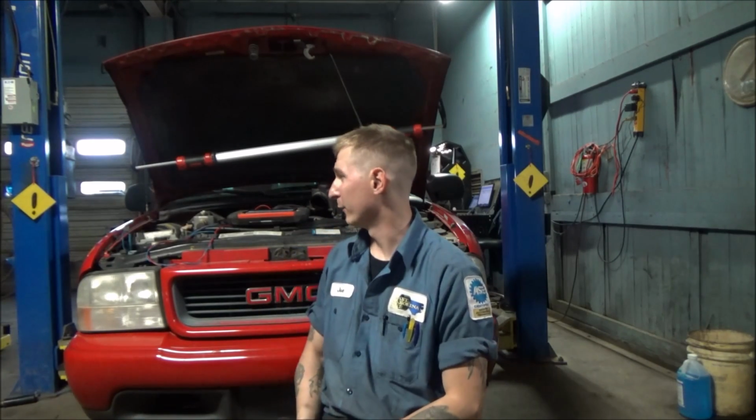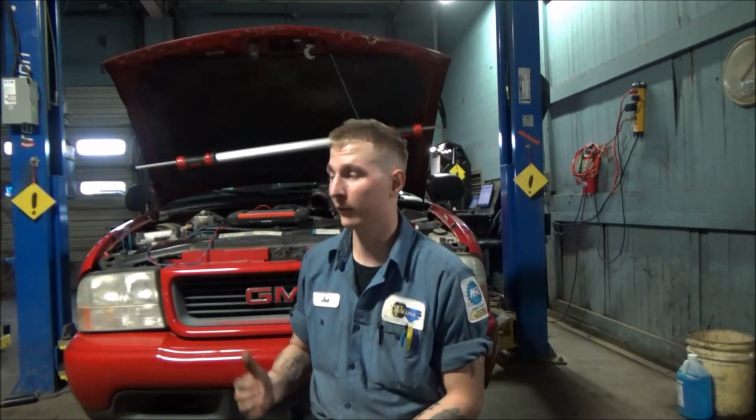You guys will see that out in the field when you're performing troubleshooting on vehicles. You really need to be focused on what's easiest to test, what makes the most sense to test. And given what we had on this vehicle, we could hear that relay clicking. That told us that most likely it was probably good, not 100%. And that really pointed us to go towards the air pump and motor. The air pump motor and the solenoid itself is the potential cause of this. So that's the direction we took.